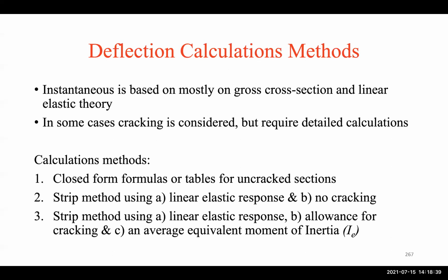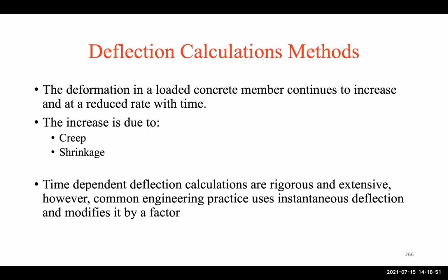So typically in the design of concrete slabs, we start with elastic deflections, and then we multiply that by a factor to determine the long-term deflection, which we will talk about, and that's basically how we do it. But sometimes we have to do detailed analysis of concrete floors, and I've done that in actual projects, considering the spans that we have.